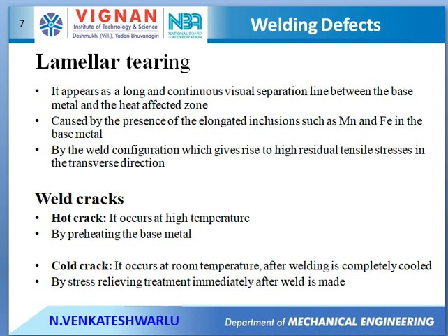A hot crack can be prevented by preheating the parts to be welded before starting the weld. And a cold crack can be rectified by subjecting the weld, immediately after completion of welding, to a suitable heat treatment process.